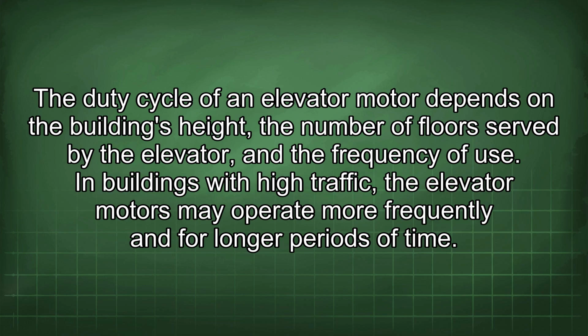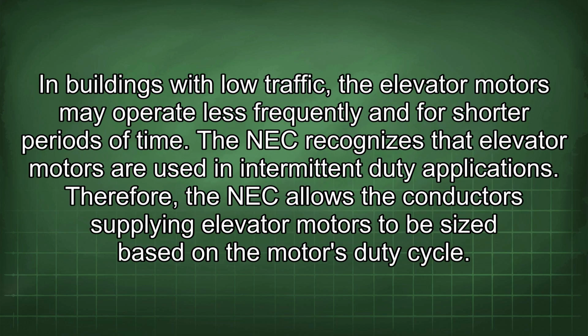In buildings with high traffic, the elevator motors may operate more frequently and for longer periods of time. In buildings with low traffic, the elevator motors may operate less frequently and for shorter periods of time. The NEC recognizes that elevator motors are used in intermittent duty applications. Therefore, the NEC allows the conductors supplying elevator motors to be sized based on the motor's duty cycle.